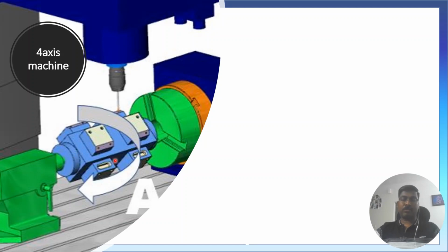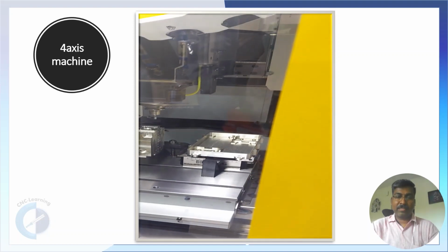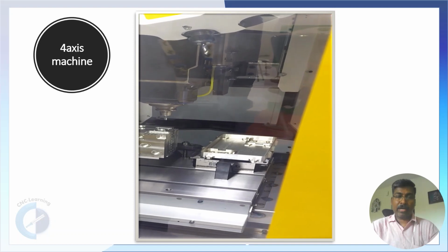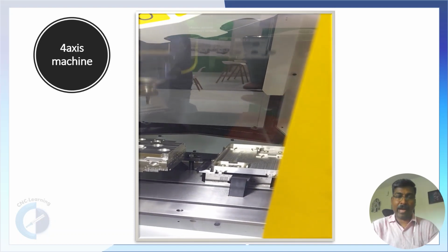The axis which is rotated about X axis is called A axis. About Y axis it is called B axis, and about Z axis called C axis. You can see a small video of a 4-axis machine. You can see this rotary axis is about X axis, so it is called A axis.